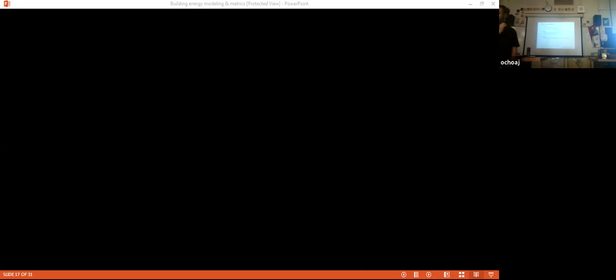So could as-built be like the finished project? It wasn't on the paper, but it's just finished. Yes. And what they do now, the VDC approach to as-built, is you bring in a laser scanner. You put a laser scanner in the middle of the room, you stand back, and it scans the whole room. It gets all the ducts and the pipes and everything, and then that goes into the as-built model. So then when the next person comes in to remodel the building, they take the as-built plan and start designing from that.